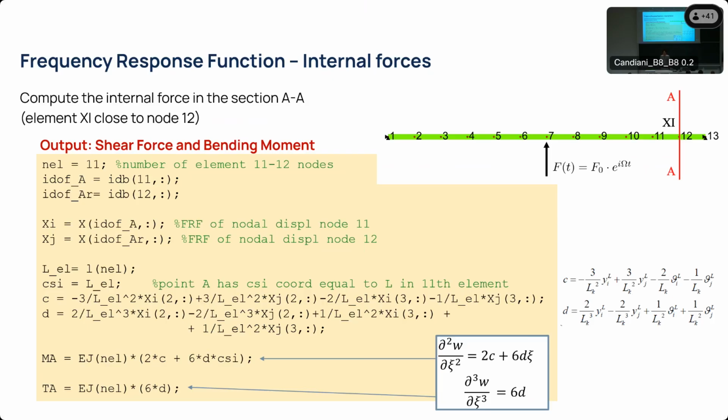So what you have to do is iterate the cycle for each of the frequencies you want to investigate, and for each of the frequencies, you will compute the relative displacement of the nodes. You will use the relative displacement for the nodes, which, remember, has a modulus and a phase, so those are all complex quantities along the computation.